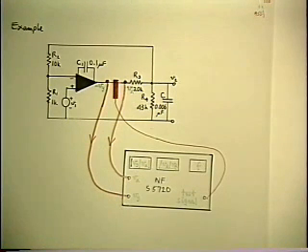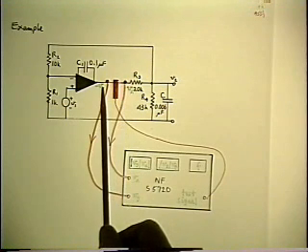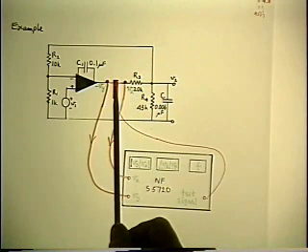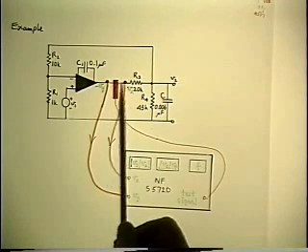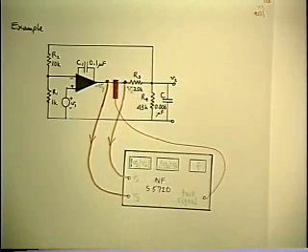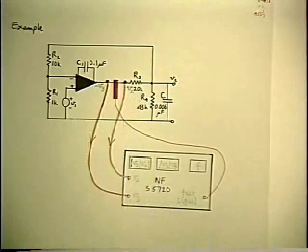Doesn't matter. Because all you're doing is measuring the ratio of two other voltages, each of which is proportional to the VZ injected voltage. So the absolute value of the injected voltage or any of the others doesn't matter. All you're doing is measuring a ratio. So the only thing that matters is that the probe injects enough signal that the Vx and the Vy can be picked out of the noise by the analyzer. That is, you've just got to make sure you're within the dynamic range. But the frequency response shape is irrelevant.